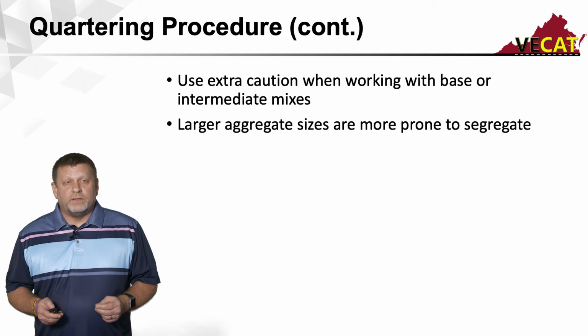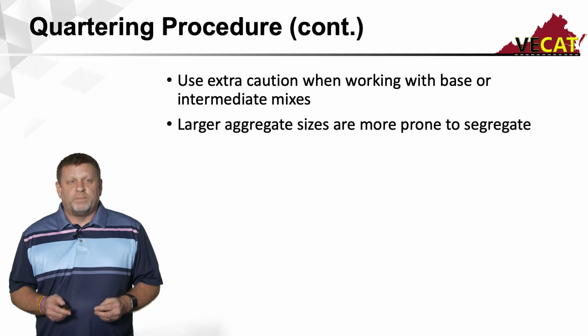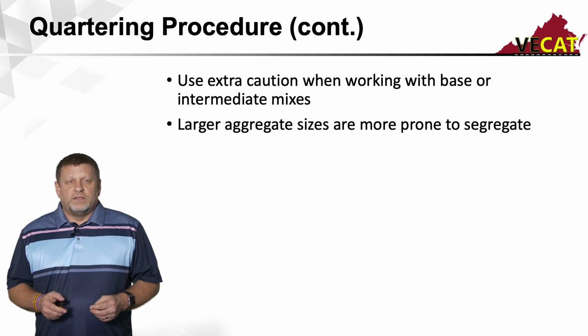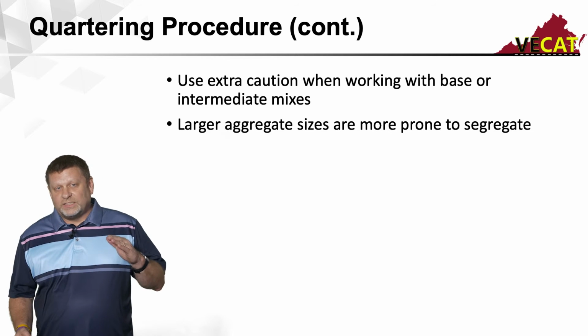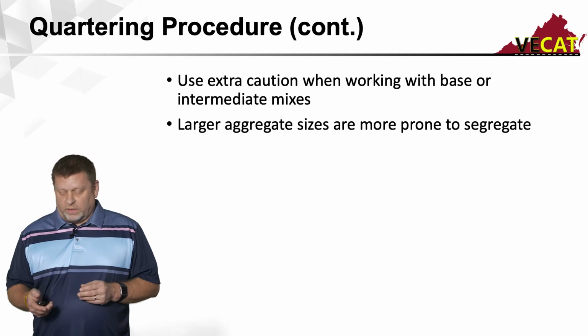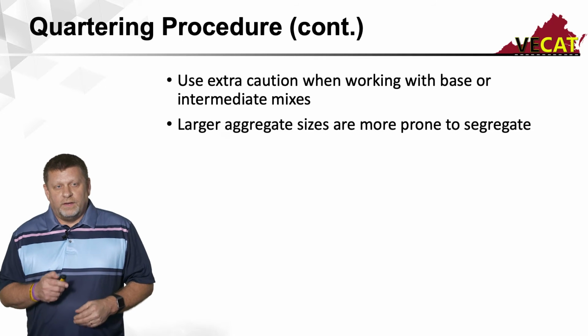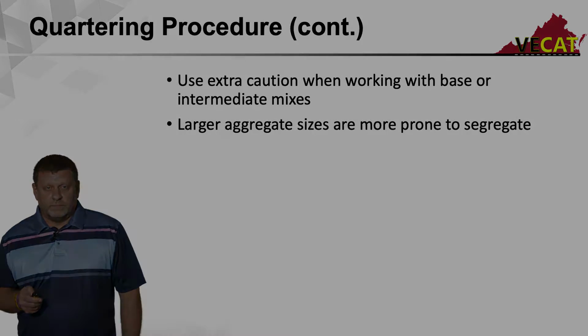One thing I want to point out, you need to use extra caution when working with base mixes or intermediate mixes. These mixes have a larger gradation band, so because of the larger gradation band, there's more opportunity for segregation. And here's a video showing you what I'm talking about.